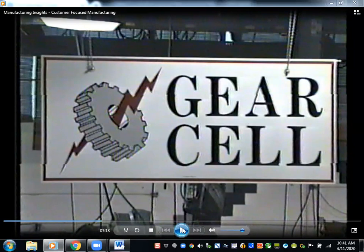And if these parts are coming from multiple cells, there has to be quite a bit of effort and attention given to implementing scheduling. So things like water spiders, parts supermarkets, finite capacity scheduling become extremely important. That's a separate topic, but all I wish to caution you about is that there are at least 2 types of lean. One is the assembly lean, and the other one is the high mix, low volume components manufacturing lean. Now, how you organize for the components manufacturing lean is left to the individual implementer's priorities.